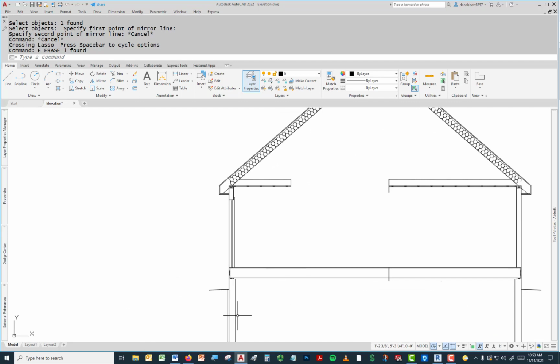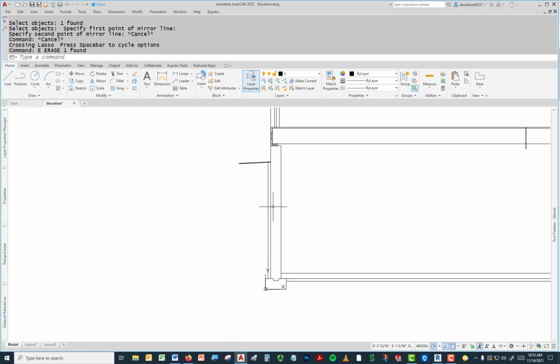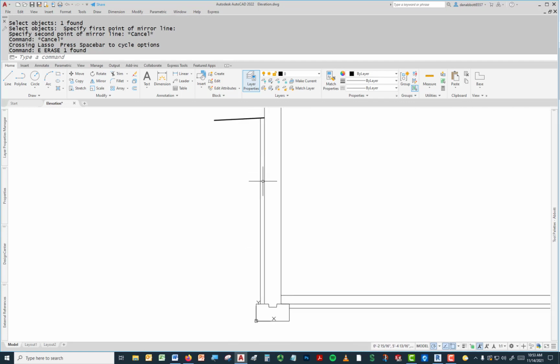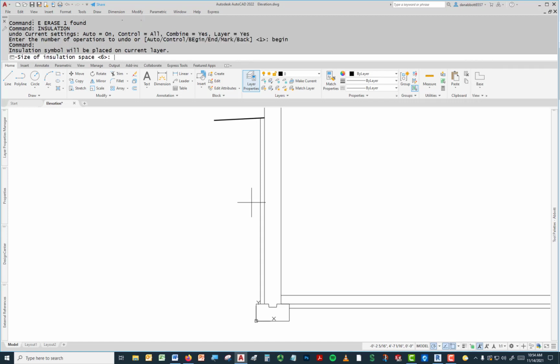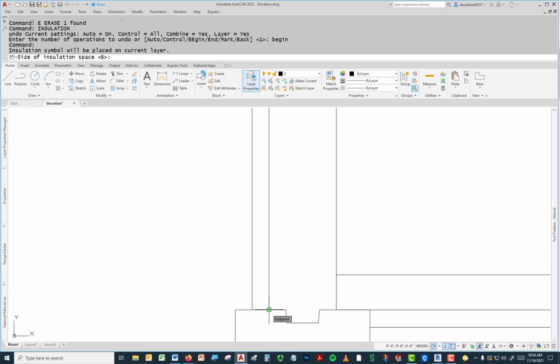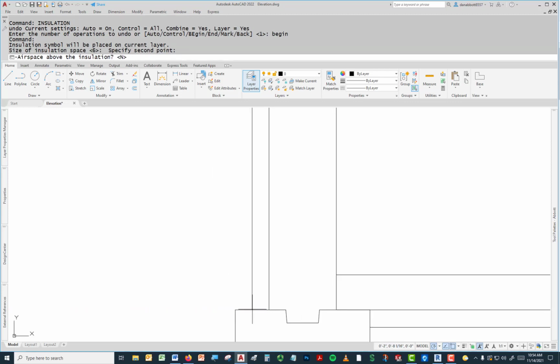The insulation program is also written so that you could use it for rigid board insulation. So for instance, that's blue board, the rigid extruded foam insulation that might go on the outside of a foundation. So if you go and use the same program, and again, as you start typing it, it pops up. Now, what's the size of my insulation? I could type that in. That's 2 inches.